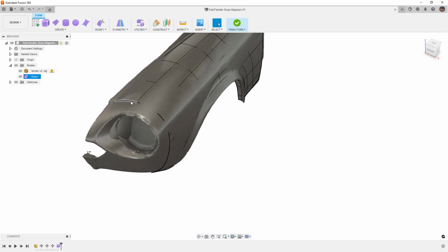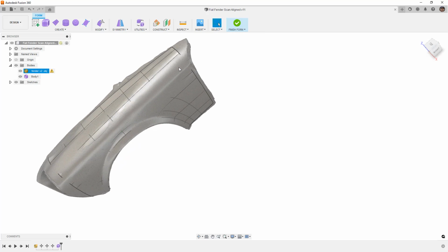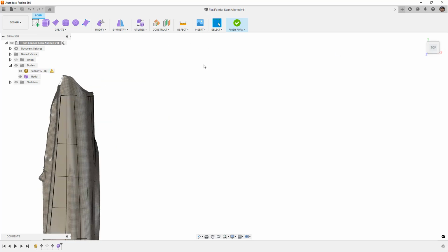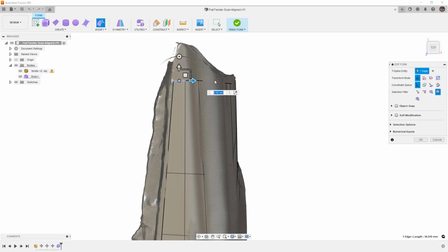At this stage, I want to begin pulling this forward, and I also want to begin pulling this back. I really need this to start to match the shape before I add that detail, that edge there. I need to begin matching that shape. So a couple ways that we can do this is we can manually start pulling these edges back and see if we can get it to match that shape. Generally, I would not do this in smooth display.